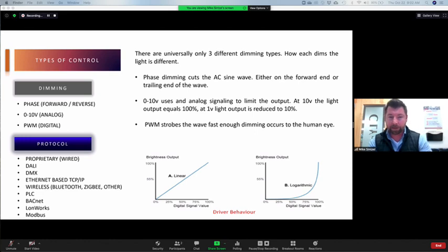One of the things that lighting designers should strive towards is keeping unison linear dimming or unison logarithmic dimming for areas, not for an entire project, but for zones. And what I see coming in from the lighting designers all over the place is a mix of stuff, because they mix fixtures and they're looking at aesthetics over electrics. So electrical characteristics.